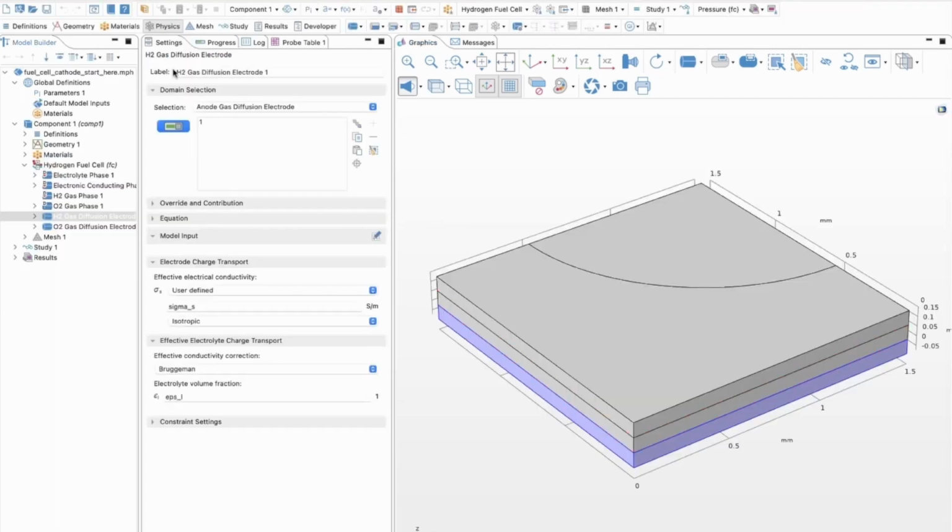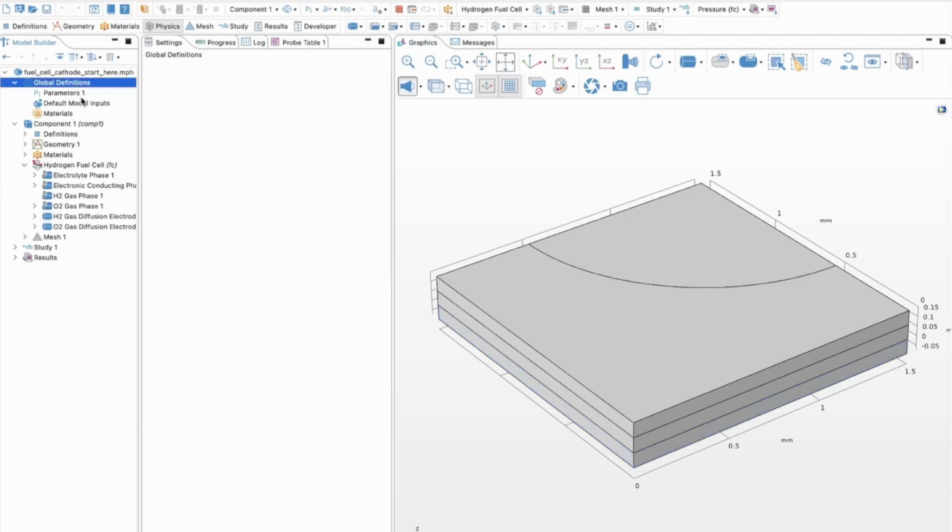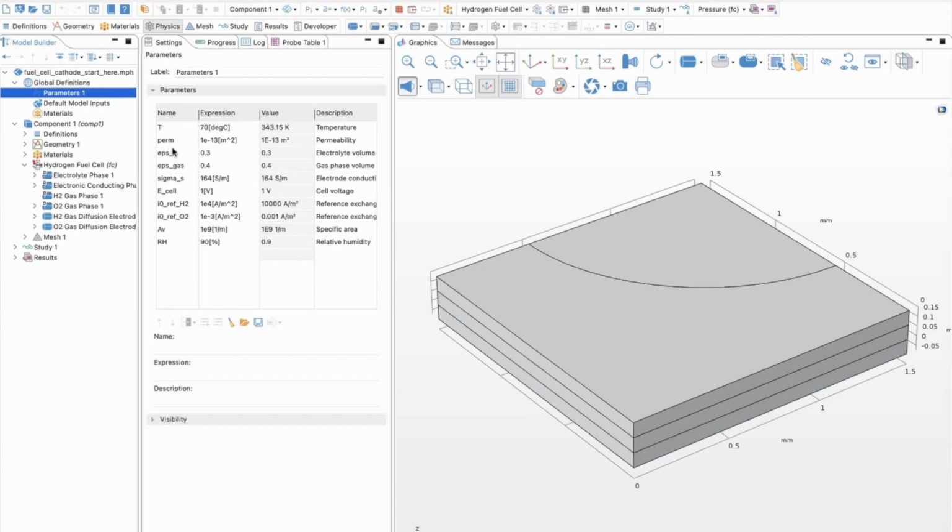Okay, so we have the model here. So let's go back to the very top. So we have the definitions here. So if you want, we can set up the parameters here at the very top, since wherever you can click on that parameter, material parameter, or boundary condition parameter in the mesh, parameter in the study node, literally wherever you can click, that can be parameters. So you can set up these here. So these are some values that we are going to use.